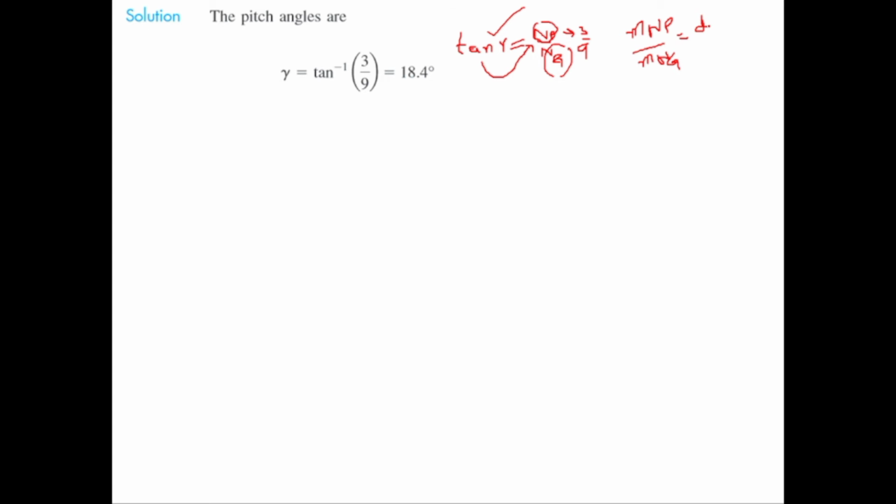First of all, we will try to find gamma and capital gamma. Tangent of gamma equals np divided by ng. Now multiply module m in numerator and denominator, as m into n equals diameter d. So tangent of gamma equals dp divided by dg.